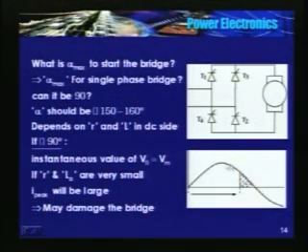Why? See the waveform here. The input AC, RLE is a load, E is 0. Say inductance is very small here. I am assuming that there is no filtering inductor in the DC side. Of course things do change if there is a filtering inductor here. Now the current is limited by R itself, which is very small. Armature resistance is very small for a motor. Again, armature inductance is also very small.